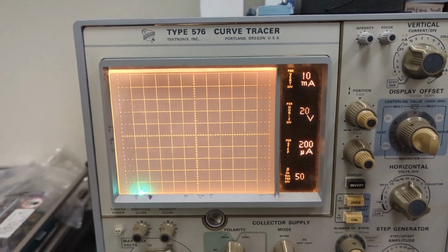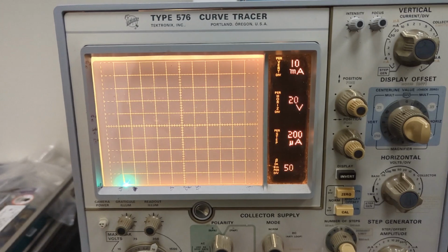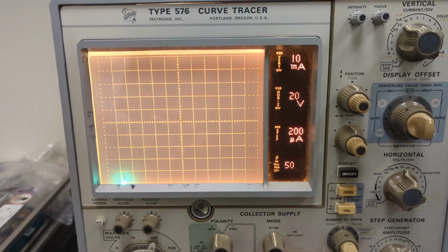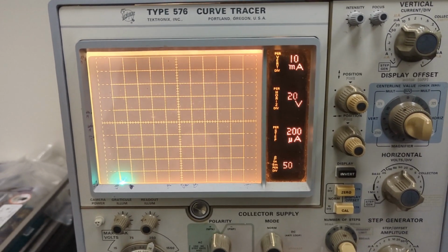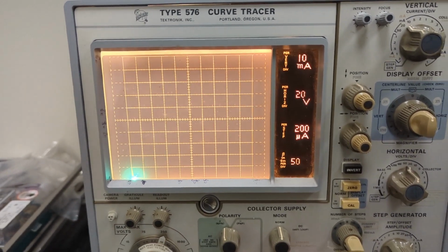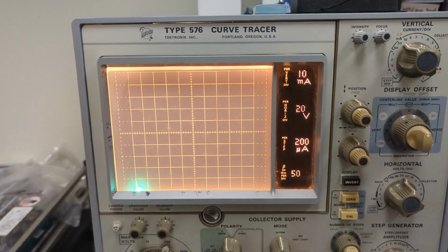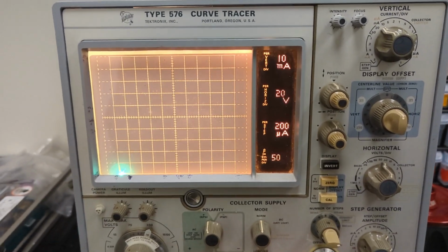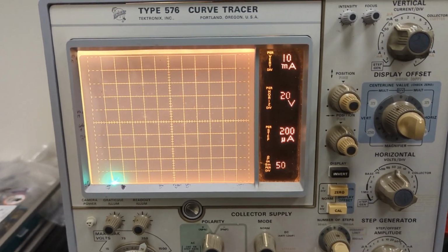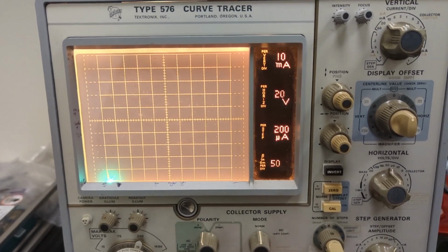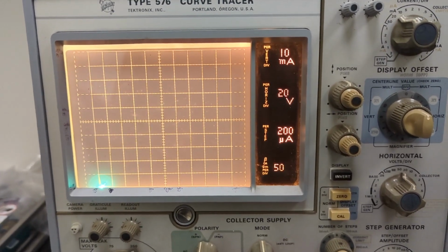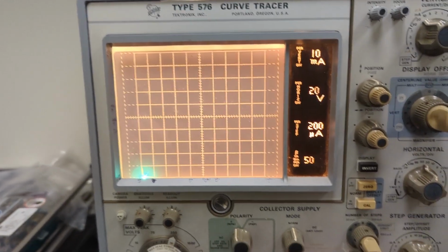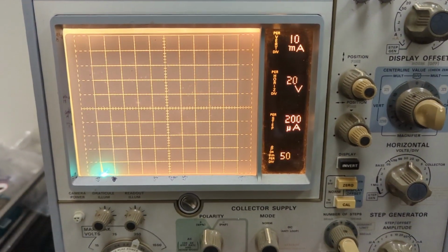I was getting it for all of the other series pass transistors, so I thought maybe there was something wrong there. So I disconnected them. Q1 is the positive 100 volt series regulator. Then there's also the negative 100 volt series regulator. Both of them are the same part number, an HP proprietary part number. So unfortunately, I can't find much information on them. But anyway, I disconnected both of them so I could compare the two.